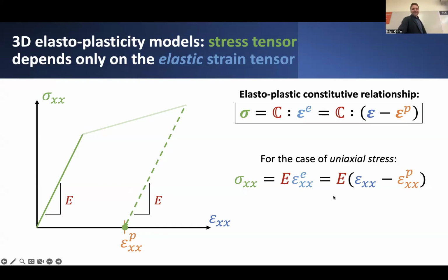However, it is rather convenient and nice to notice that if we were to look at the particular case of a uniaxial state of stress, we could still come back and find that the relationship between elastic axial strain and the actual axial component of stress that would result in that uniaxial state of stress follows directly from this expression.